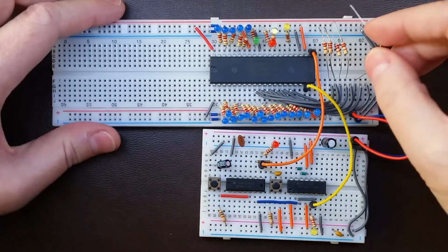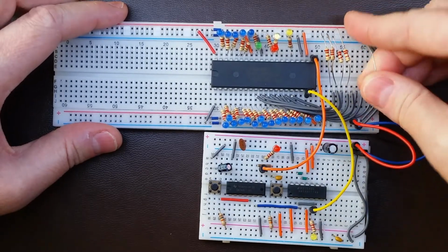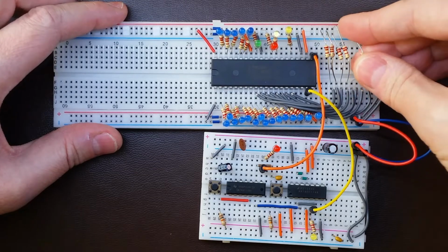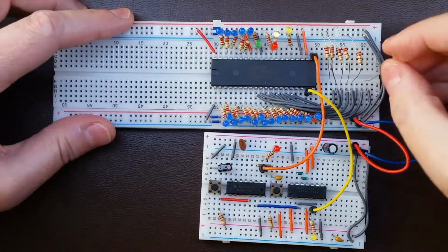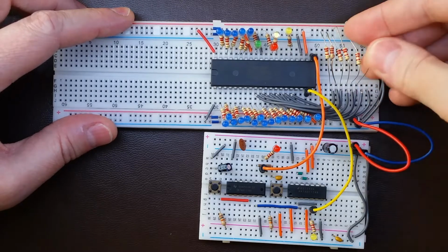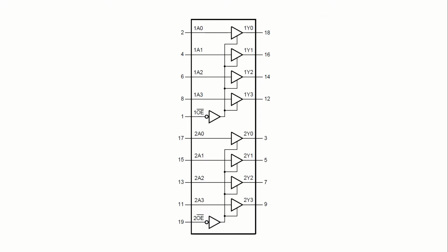Do you remember when we tried to simulate the program memory with 8 resistors which set zeros and ones on the data bus to form the NOP machine code? Today we will do a similar thing, but more digitally if you want. We're going to use the 74HCT244, which is a tri-state 8-bit buffer which drives its outputs only when an additional signal is given. This signal is very similar to the CE or chip enable in the memory chips. If you need more explanation of what a tri-state output is, look around my channel, as this is explained in my separate series where I talk more about the 7400 chips family.